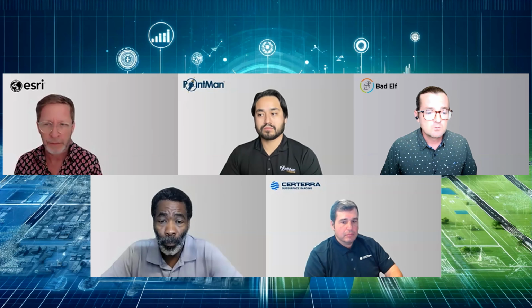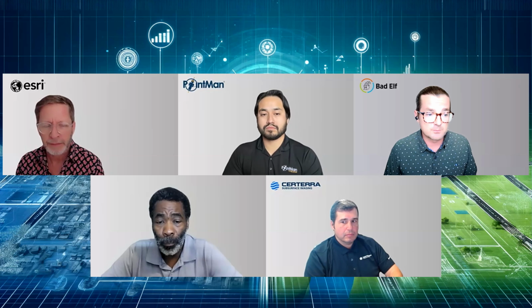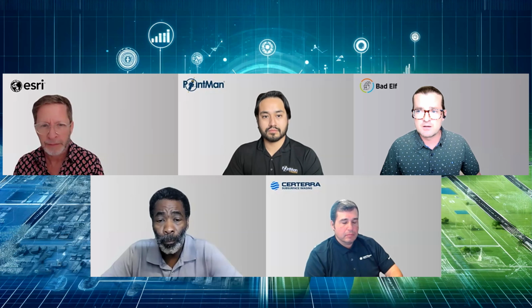So what happens is that will get you, say, from sub-meter accuracy on most devices down to centimeters or fractions of an inch. And so be aware what service you're using, how far that distance is to that service, or that baseline distance to the CORS, whether it's Bad Elf or some other provider. Talk to the people you're getting your GPS and equipment from. They should be able to discuss this with you.